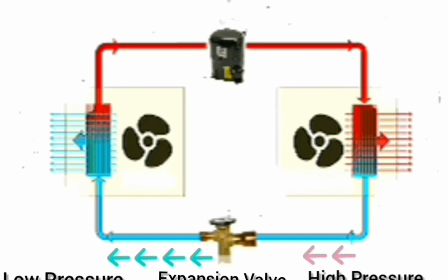What expansion valves do is restrict refrigerant flow, so it has more space to expand. This causes lowering of refrigerant pressure and leads to a small portion of liquid refrigerant to flash to gas, which cools down the liquid refrigerant. The main idea is that when you reduce pressure of refrigerant in a fixed volume, it will result in a decrease in temperature of refrigerant and vice versa.